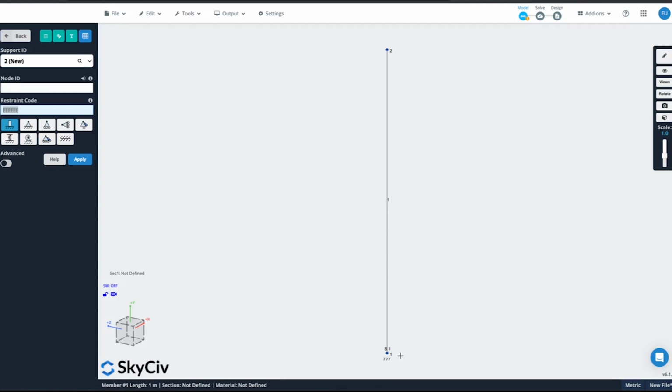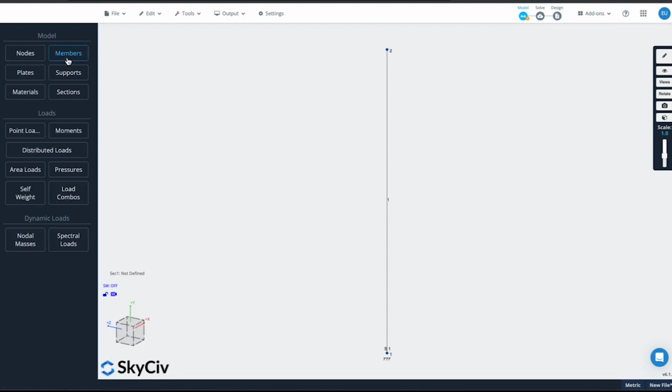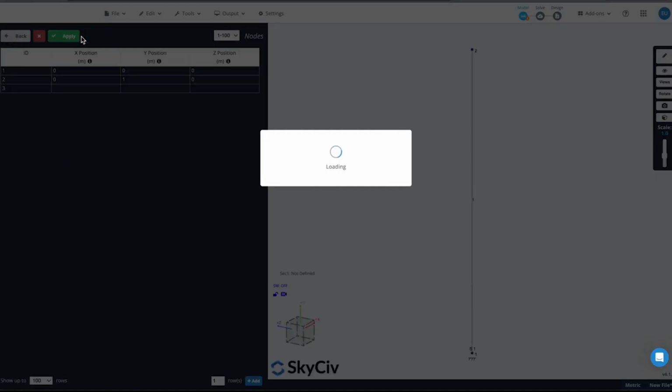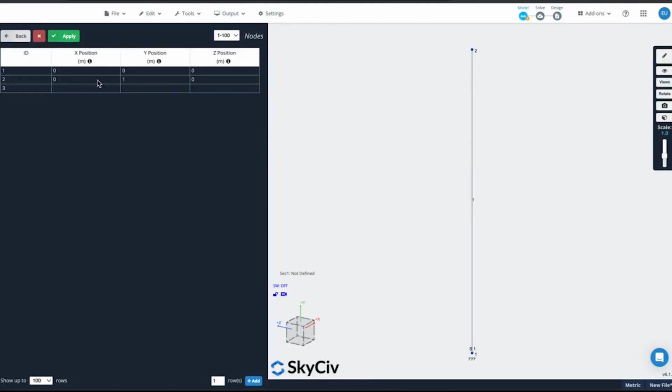I don't want it to rotate at all. Just be fixed in all directions. Say we had a different condition where, let's try to do a cantilevered beam now, or like, let's do a simply supported beam. So I'm going to change the nodes for 2. As we're going to do a simply supported beam, let's just have it starting here. We'll go maybe like 10 feet out or 1 foot out. So we go back to 0. Let's just go 1 foot out in the Z direction.